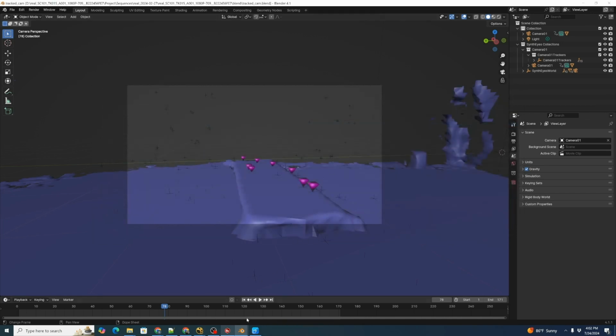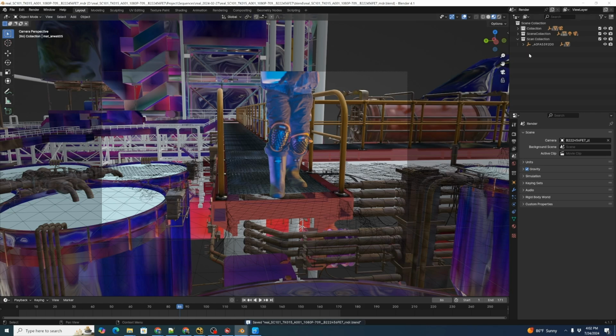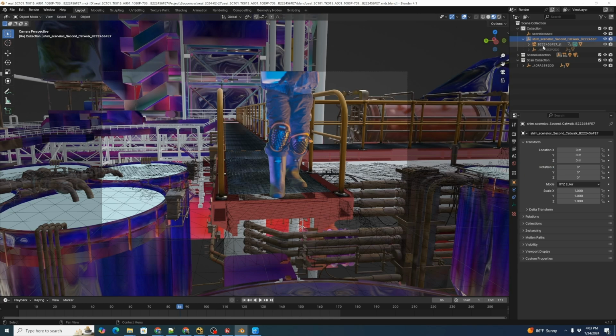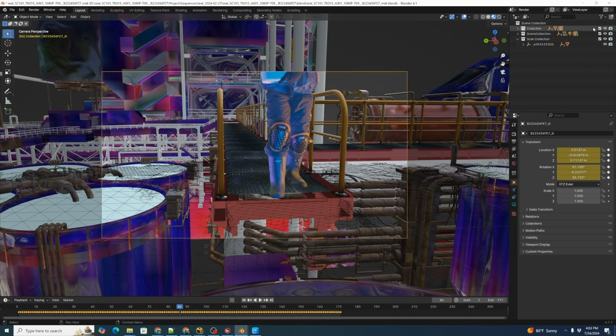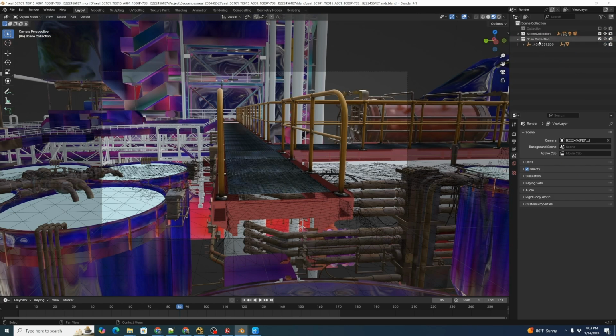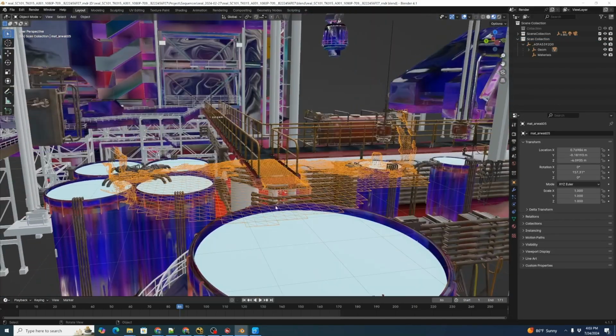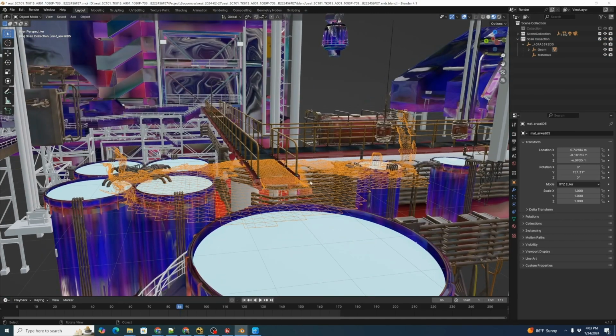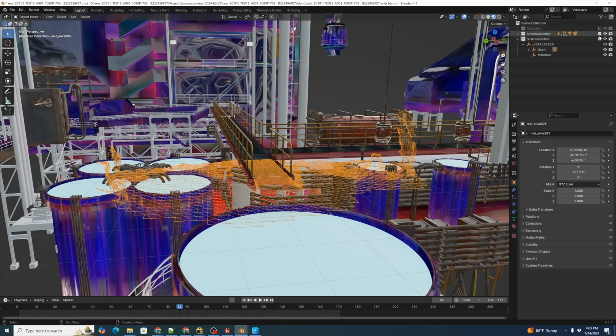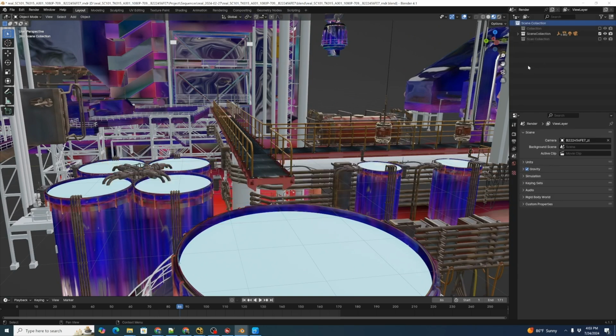Now we're going to go back to our other Blender file. Here is our original Blender render file. And before we bring in the Syntheyes information, let's turn off some things to avoid confusing ourselves. The initial collection has the jet set tracked camera in it, as well as the image plane. We're not going to need that, so we're going to turn off that collection. This is the scan collection. And so if I highlight the scan, that has the geometry from the LiDAR set. We're actually going to bring in our new geometry along with this from Syntheyes, so we don't want this either. So I'm going to turn off the scan collection. I'm going to highlight scene collection because when we append the Syntheyes scene, we want it to come in under the scene collection. All right, so let's go ahead and save that.